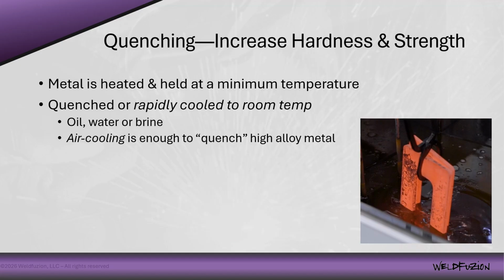All right, we're going to cover this more in the steel module, and quenching is always happening in some way when you weld. So keep that in mind. The air around the weld is taking heat away, right? The base metal itself, based on how big that structure is that you're welding on, is sinking the heat away. So that makes a difference. So unless you're actually applying heat to maintain a temperature, you're seeing some form of quenching when you're done welding. And again, that's the thing. When materials are made, they're made under strict guidelines for heating and cooling rates. And when we weld on them, that stuff goes out the window, right? And then we get unpredictable results. That's what this whole class is about.